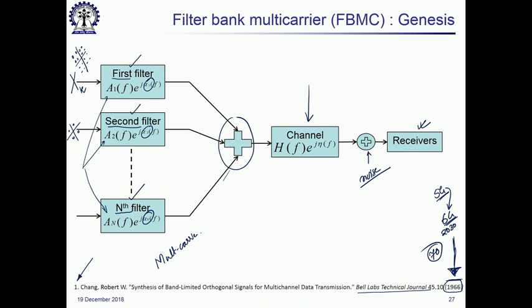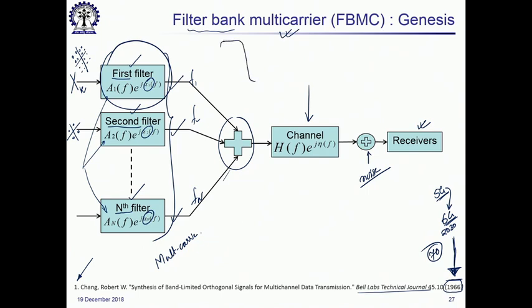So, the fundamental difference with OFDM is that there are filters on each of the carriers, and there is a whole bank of filters, and hence it is a filter bank, and they appear as multiple carriers operating at different frequencies. So, there is a multi-carrier system, and the advantage is that one can design these filters in such a manner that the transition band is very sharp, and yet one has this multi-carrier structure. So, although there is multi-carrier structure, overall one can have very tight spectral characteristics, by virtue of which a highly efficient system can be realized.